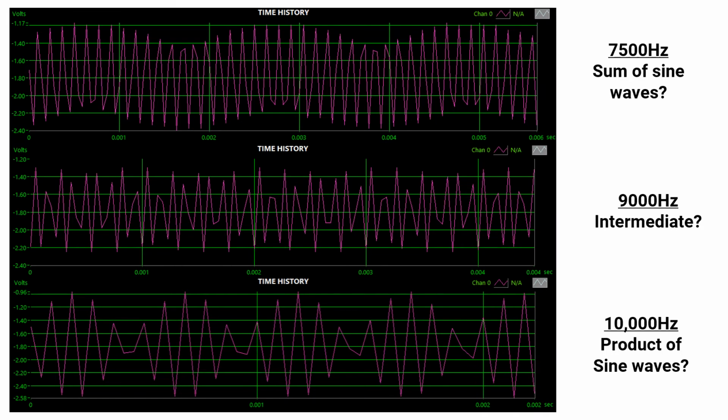You'll also notice that the peaks are very sharp and straight, and that's because of the amount of data points that the digital sampling is taking. I tried to turn this up, however, it crashed the program every time, which leads me to think that we were hitting the top end of the number of samples per second that our data acquisition software could actually hit.